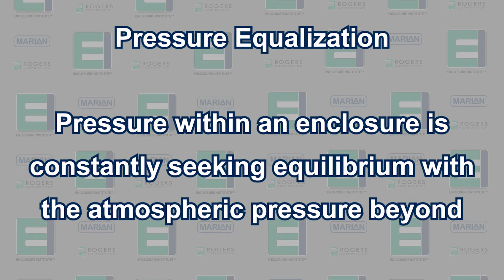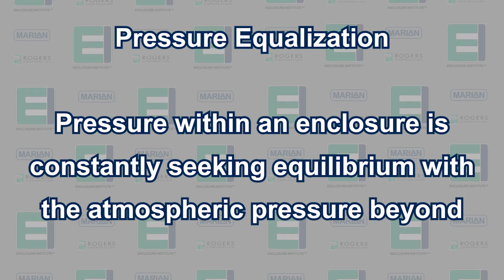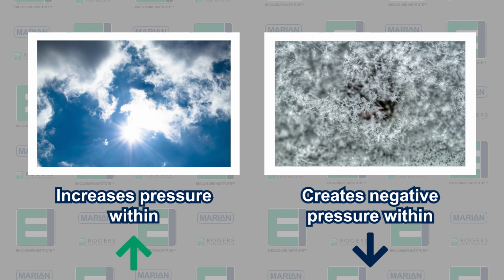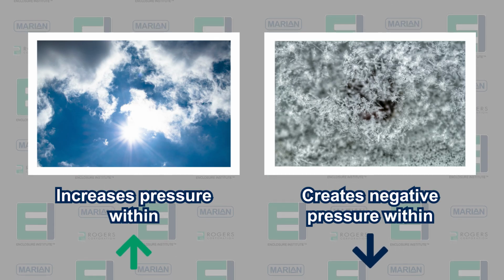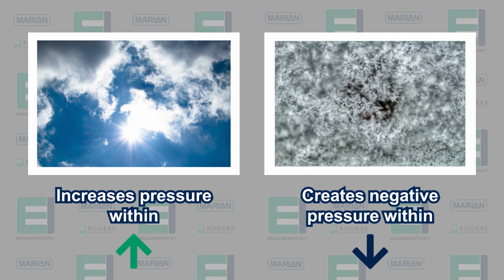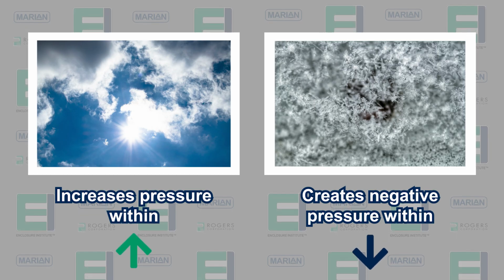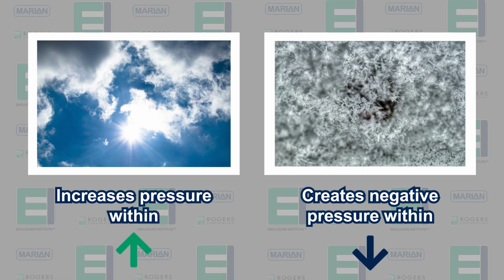This is why the half-filled water bottle that I took on the airplane started to implode by the time we touched down. Inside the device, the rising temperature will increase the pressure within. Conversely, cooling temperatures will create negative pressure. These changes in pressure put stress on the device's seal. This can cause leaks, which could mean failure to achieve a desired IP or NEMA rating.